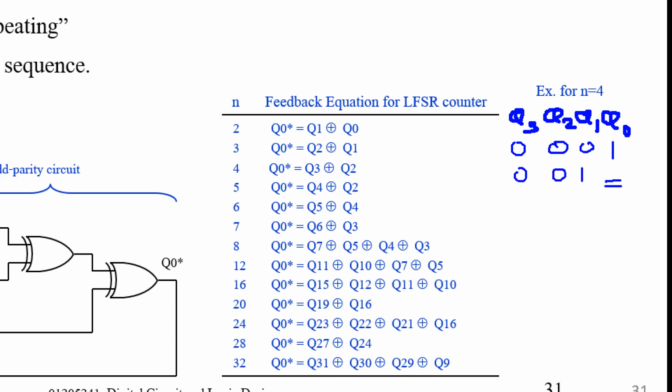How about this? For this you must consider 4 bits, right? Are Q3, Q2 different or not? If the same, then 0. If different, Q star is 1, right? Q0 star will be 1 when Q3, Q2 are different. Okay, for the next state, again, copy this.